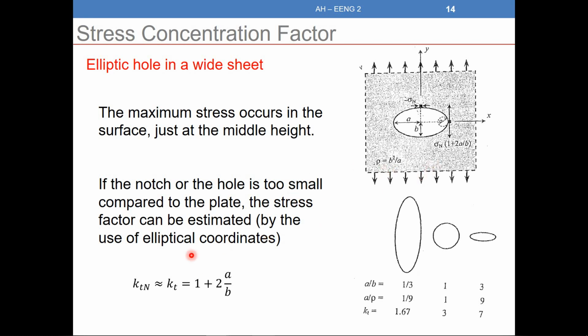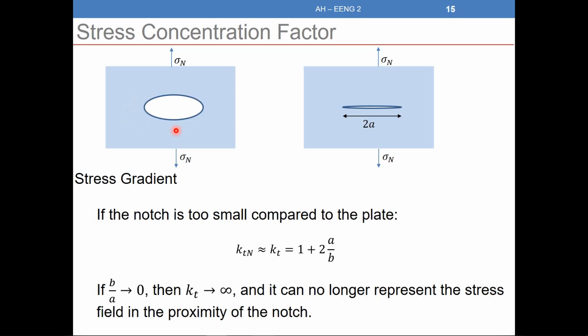The stress concentration factor, as we said, is used in the case of an elliptic hole, and the hole, the notch, or the fillet are geometrical features that I put in the design. So as a design, I intend to put inside it a hole that can be elliptic or circular, or a notch, or I can put a fillet. So these are parameters that I can control. At the beginning, we said also that if I want to model a crack, and now we go back to the crack because that's our objective, we take it as an elliptic hole, but B is very small compared to A.